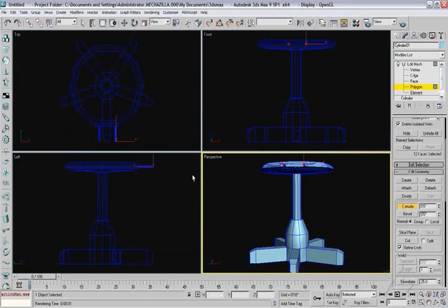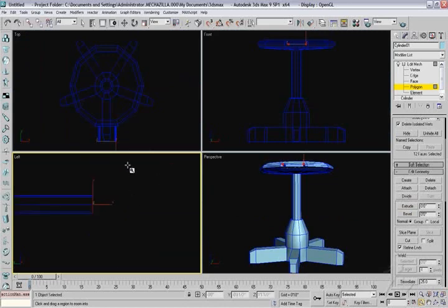Now, when you want to make a curve, what you do is make short extrusions, and as you extrude, I'm going to zoom around the left viewport, you rotate the polygon. So it's between the rotate and then extrude. Now, a handy way of knowing how to do this is using the shortcut keys. The transform tools are set up with W being the move tool up here. If I hit W, it will give me that. If I hit E on my keyboard, it will give me the rotate. If I hit R, it will give me the scale tool. So if you hit E, that will give you rotate. And we're going to jump back and forth between extruding and rotating.